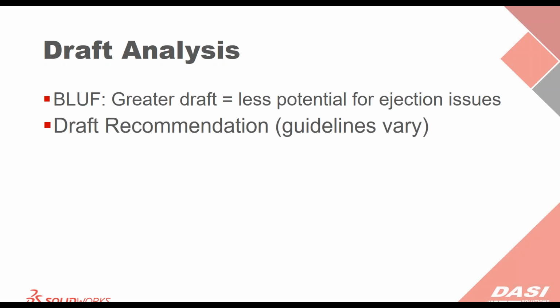These guidelines vary depending on the sources you look at. If you look at textbooks, or at specific websites of companies that manufacture tooling, they may have their own guidelines as well. I've seen anything range from half a degree to several degrees. I've seen sources say 1/8 degree up to 6 degrees. But normally 2 to 3 degrees is totally fine if you're not concerned.